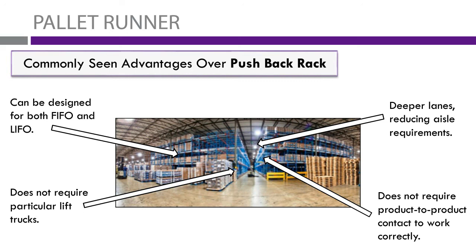And then another big advantage of it is that with pushback, you're only dealing with a LIFO system. So last in, first out. But when you deal with the pallet runner, you can actually set it up in multiple ways, where you could do a LIFO system, you can do a FIFO system, and then there's actually a couple other benefits that are offered. One of them is going to be they do offer a bidirectional option, which means that you can actually switch where the home position is.